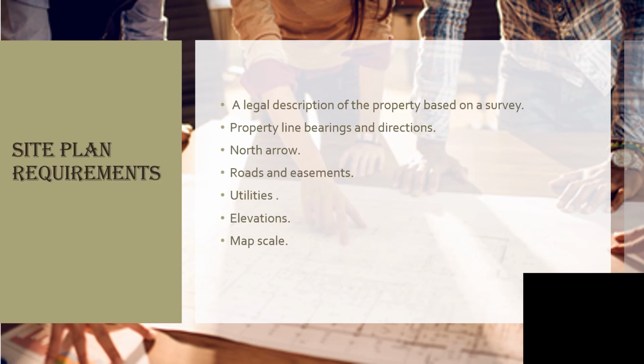Site plan requirements. Site plans can be drawn to serve any number of required functions, and all have similar characteristics, which include showing the following: a legal description of the property based on the survey, property line, bearings and directions, north arrow, roads and easements, utilities, elevations, map scale.